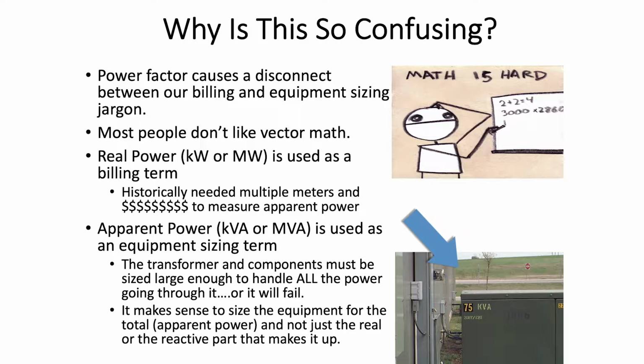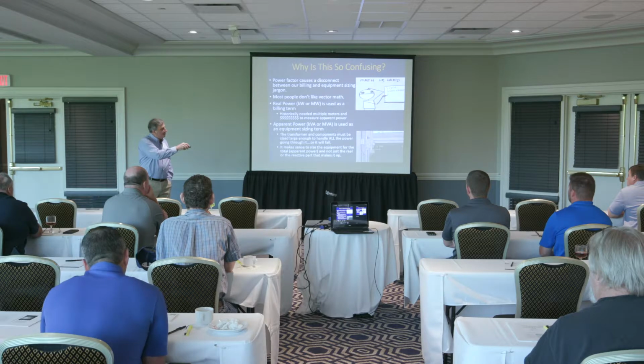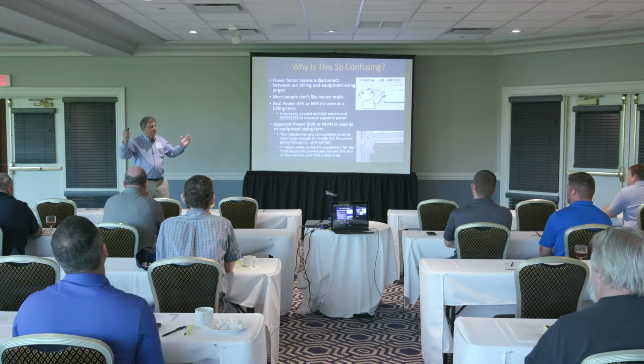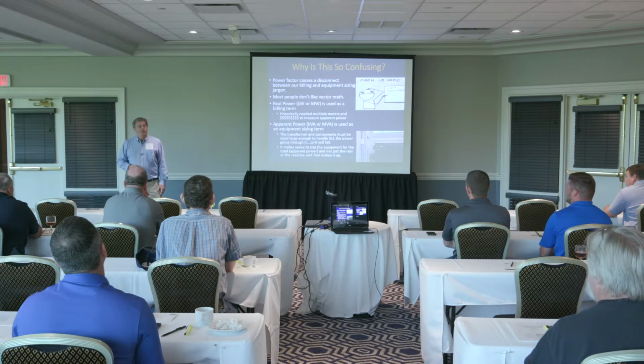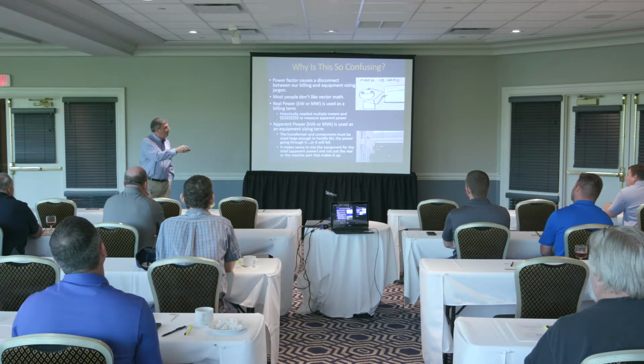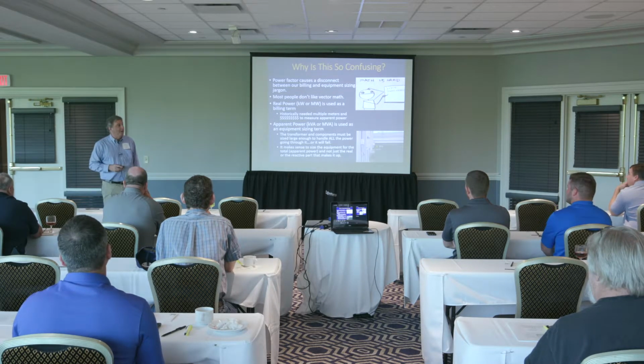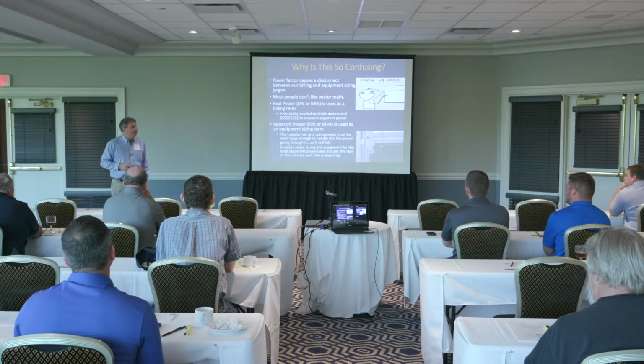When you size a transformer, what units of power do you size a transformer in? kVA, right there, 75 kVA. When that utility is measuring how much peak demand you're using, what are they measuring at that meter? Kilowatts. So we have a disconnect between our equipment sizing and our billing in the industry. And that dates back to the early days where power factor wasn't important.